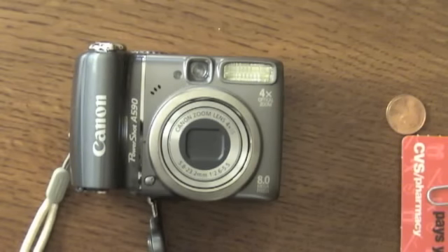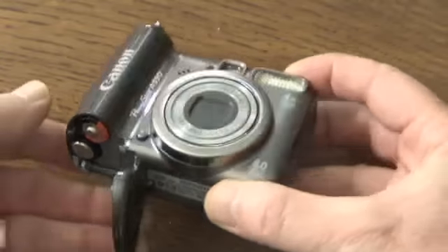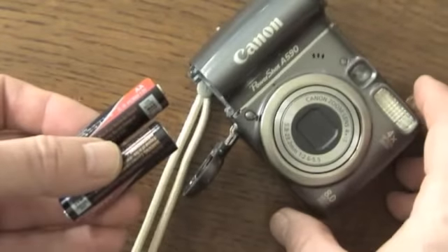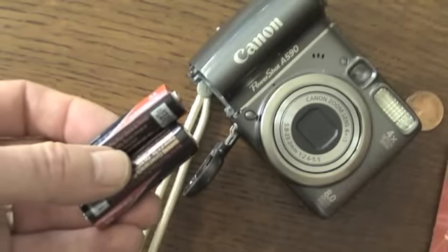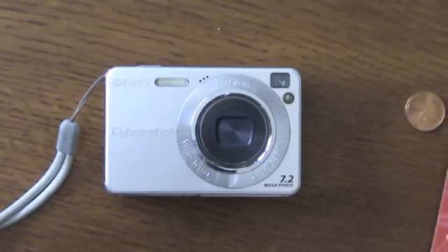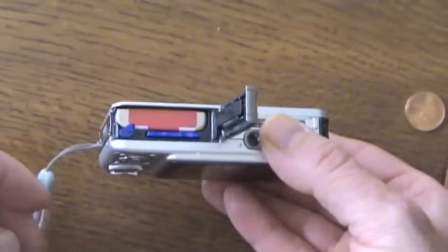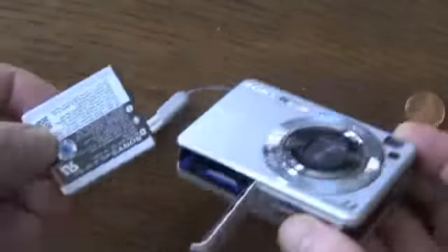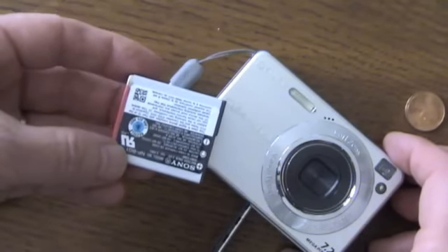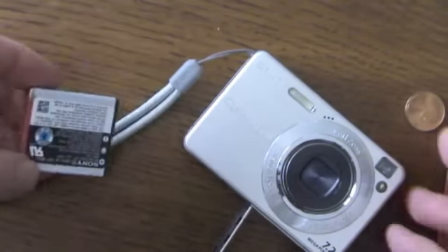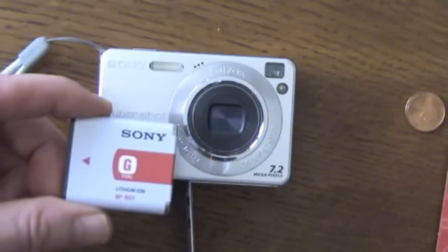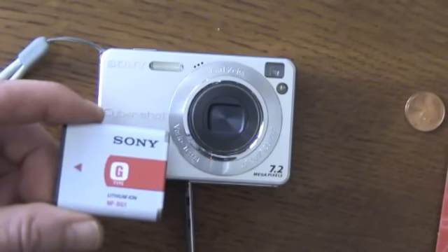One needn't look far to find cases where circuit designers have used the fact that 2 voltage sources in series are equivalent to a source whose voltage is equal to their sum. In this camera here, if we open the battery compartment, they are connected in series within the camera to provide the equivalent of one 3-volt source. On the other hand, taking a different camera, if we open its battery compartment, we find just one battery. It's approximately a 3 volt lithium-ion single battery. The difference between the two being a matter primarily of milliamp hours, consumer preference, and cost.